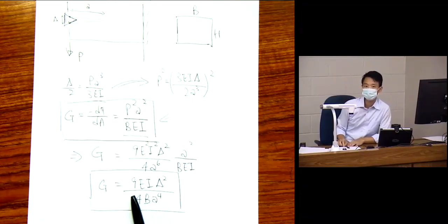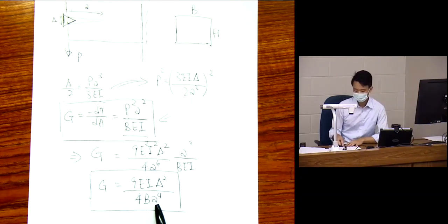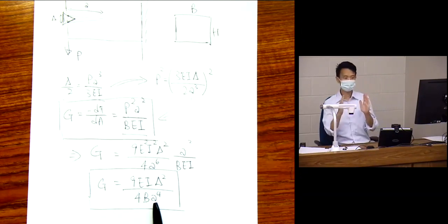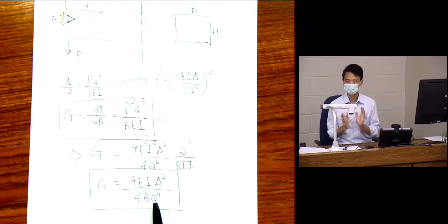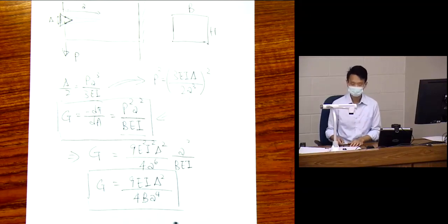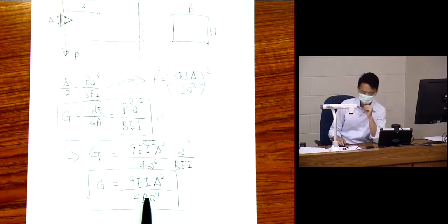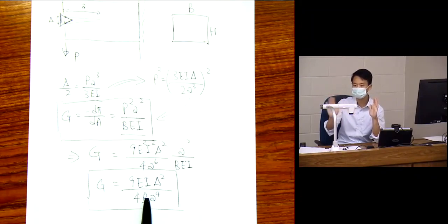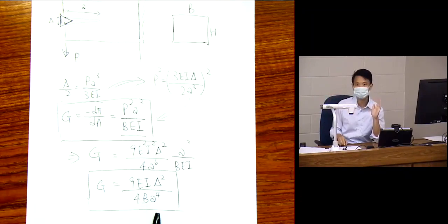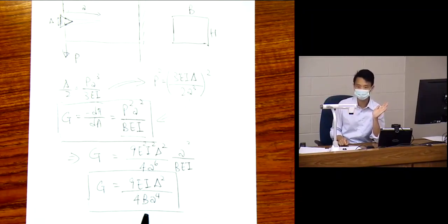So that's good. Think about this. The crack grows a little bit, and actually G is smaller now, so there's less energy available by this loading method to advance the crack. So if the fracture energy is constant, that means the fracture resistance does not change with a, then we will have a stable crack growth in this case, right?